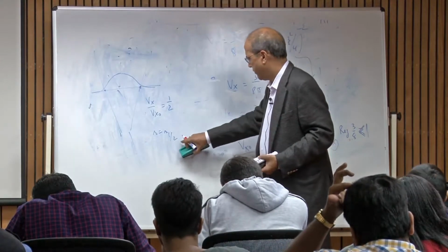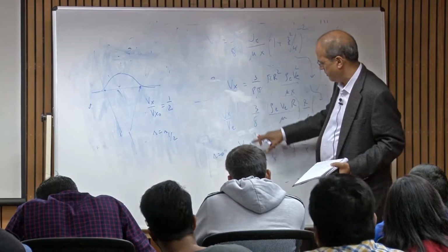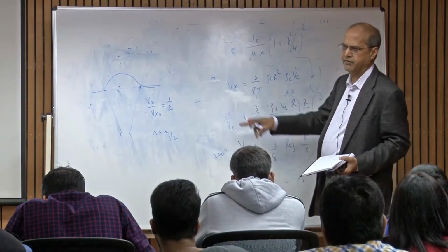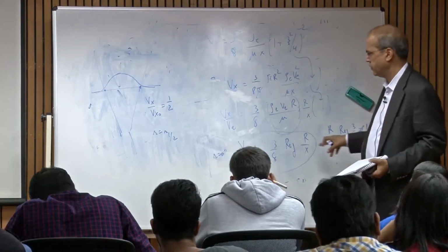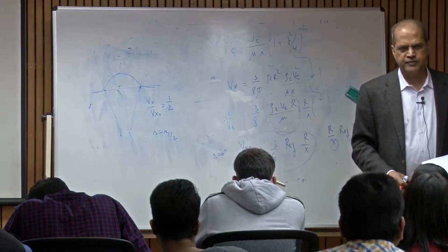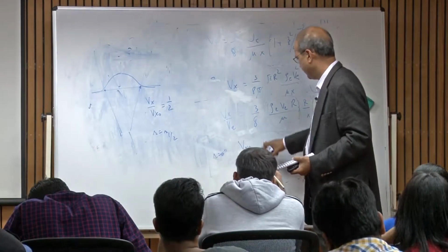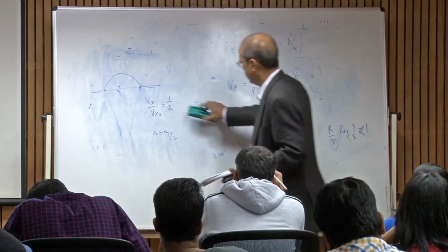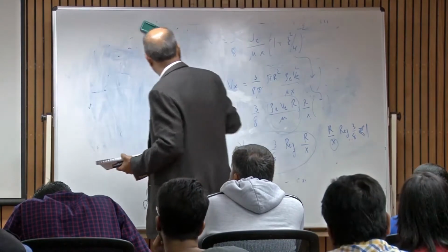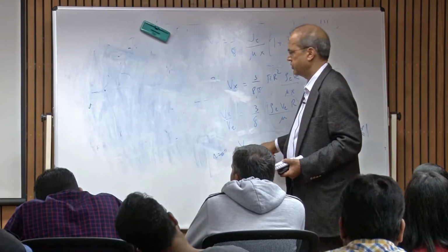So to find this r 1/2, all we need is take Vx divided by Vx0, and that ratio is 1/2. That will give us the value of small r for the spreading radius. So, take this ratio, Vx divided by Vx0.